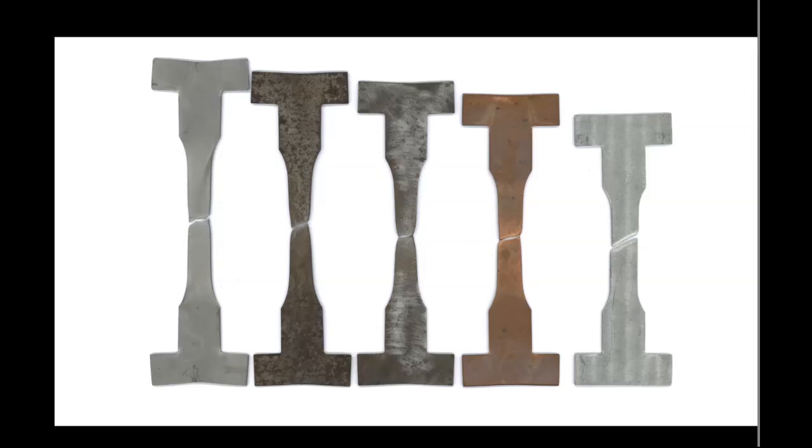Okay, so imagine you have a really brittle sample, right? A brittle sample will be like a brick or glass or brittle polymer. So it will extend out and it will not elongate, it will just break at the ultimate tensile point. Okay, that's a brittle behavior. But any ductile material will reach the plateau, start thinning at the neck, and then descend down. Okay, so that's another indication. So the difference between UTS and fracture indicates how brittle materials are. That's what this question required.